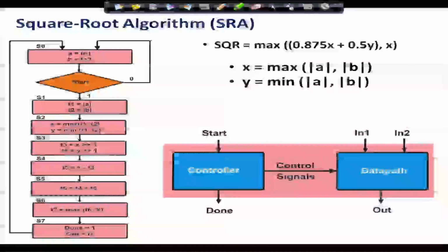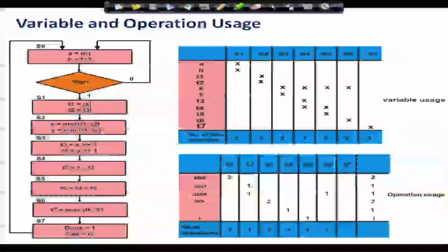So, here you see we have put up, say, 2 operations in the same control step. Before that, let me quickly explain what is meant by control step. Say at every clock cycle some operations will be done. So, I can assume each of these to be the control steps, and say I can have an addition done here and a subtraction done at the same control step.